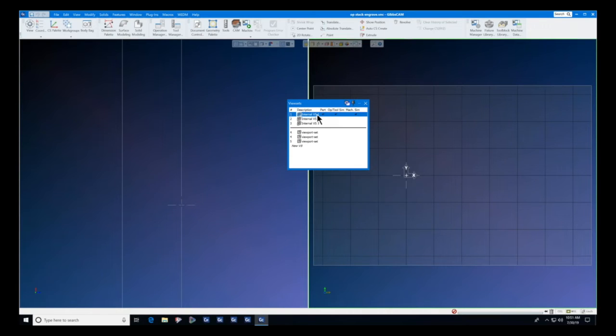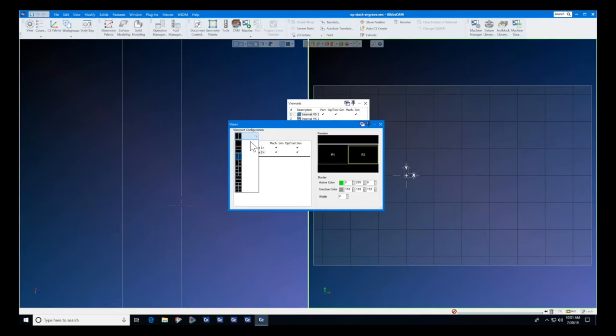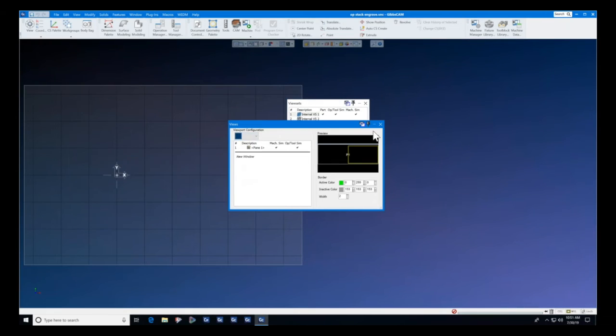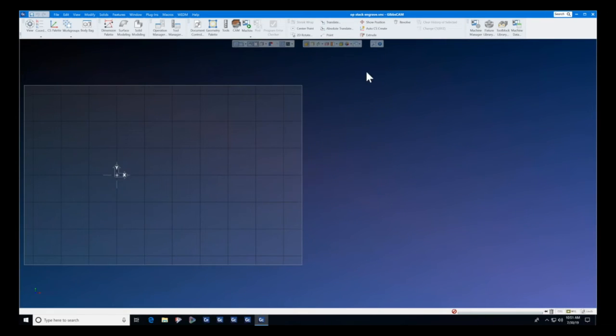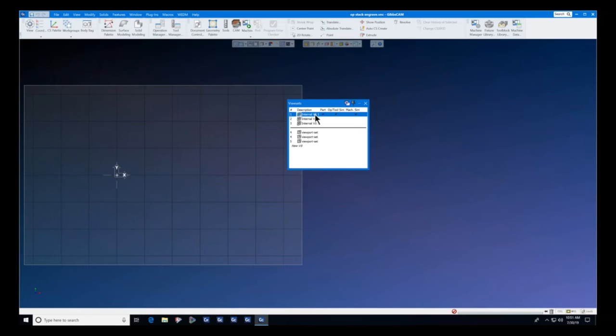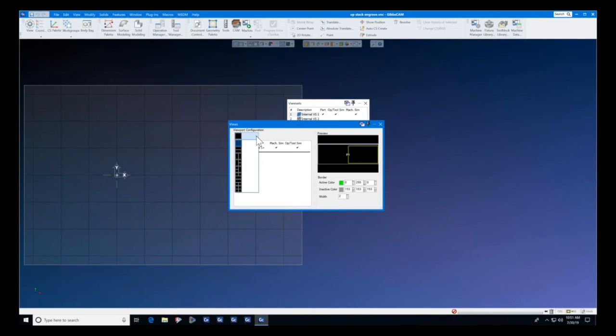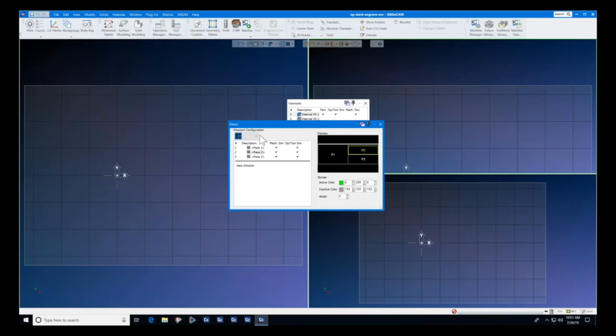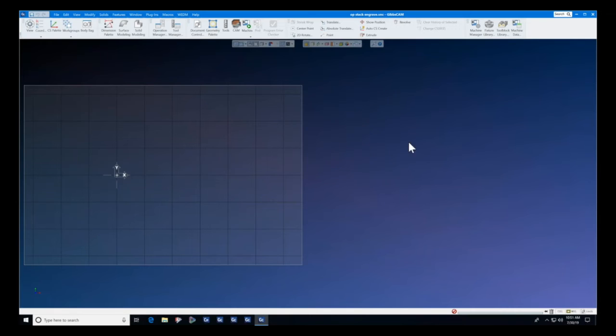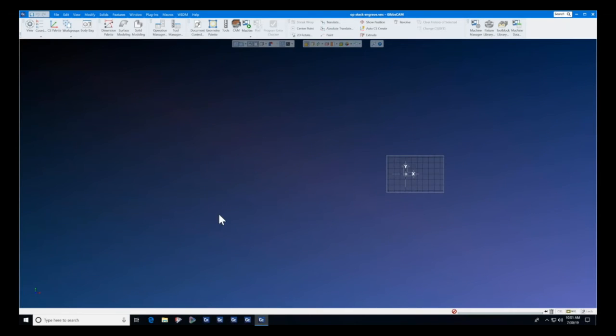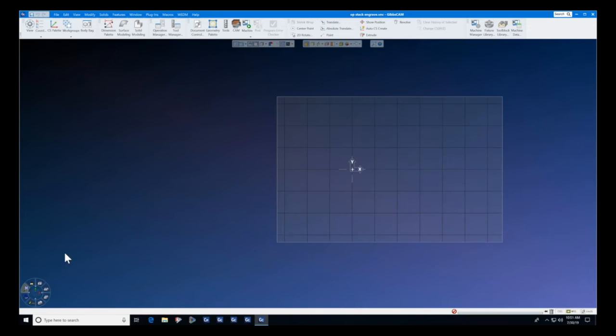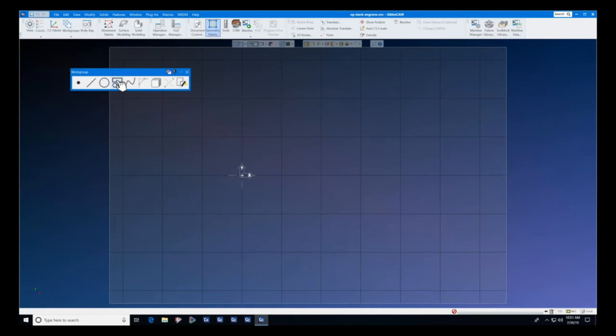We'll go to 1 viewport. And by the way, there are multiple viewports in GibbsCAM if you didn't know it. To get to the multiple viewport manager, you simply click this button and you can set different custom viewports. Once you get there, you may modify it by clicking here and setting 3 windows, 2 windows, 1 window. And there are a number of things that you can do inside of multiple viewports if you have a very large monitor like I do. So let's throw some engraving down on this part real quick and show you what op stacking looks like.